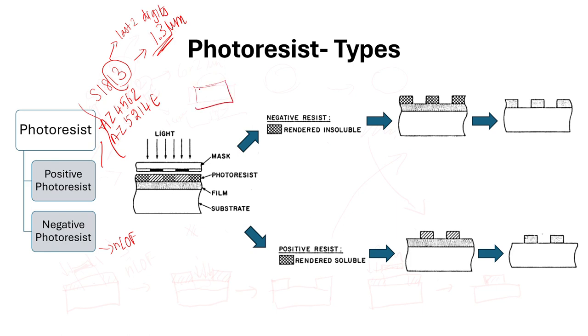Also, in the deposition process, if you want to coat a photoresist, what happens is we take a substrate, we dispense some photoresist on the substrate, and the substrate is held by some sort of vacuum in the system. After that we input the spin duration as well as the spin RPM.